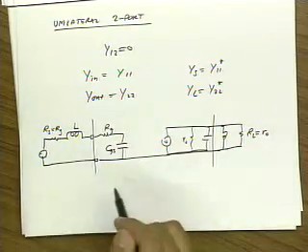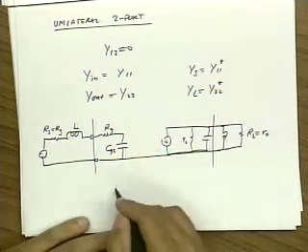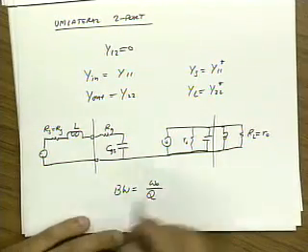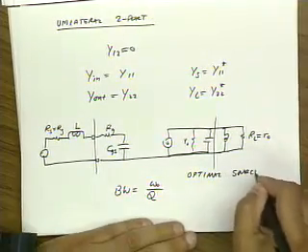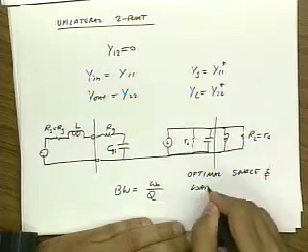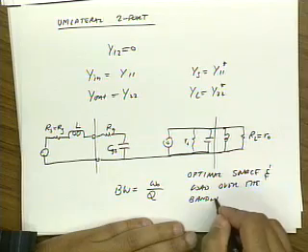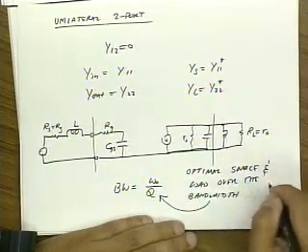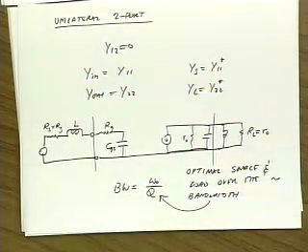And so what I'll find is that this optimality condition holds over a bandwidth which is determined by the quality factor of my circuit. So I have optimal source and load over the bandwidth. When I say over, I mean approximately over this bandwidth. I have a good input and output match, and therefore I have maximum power gain. All right?